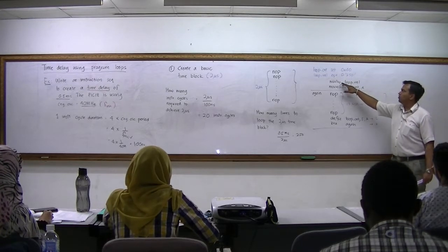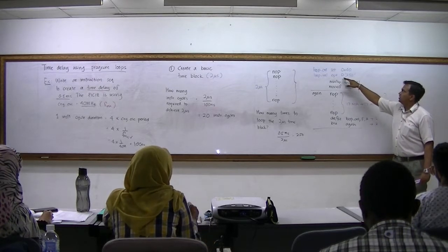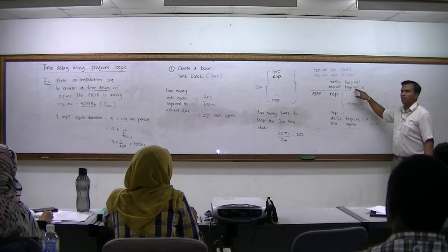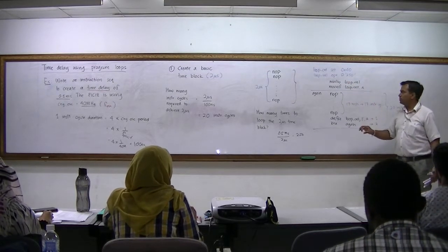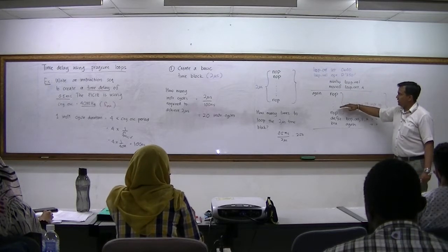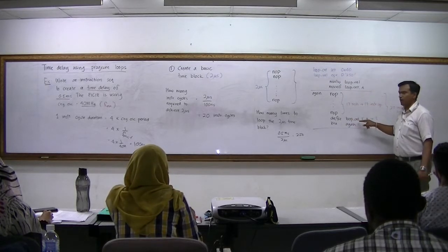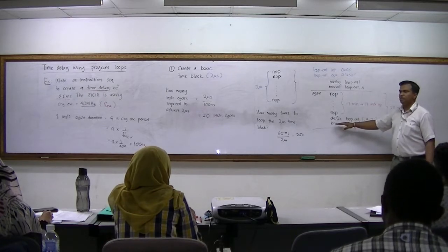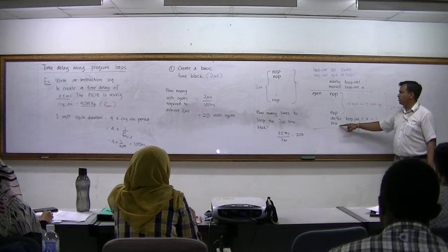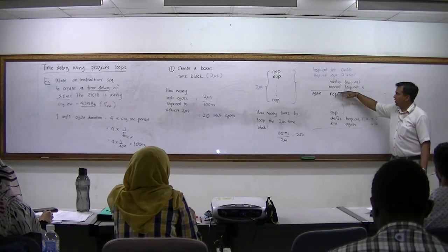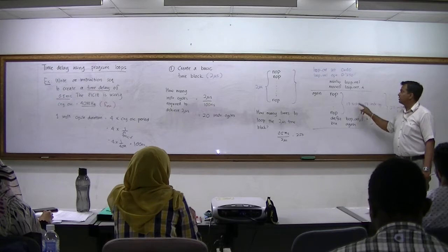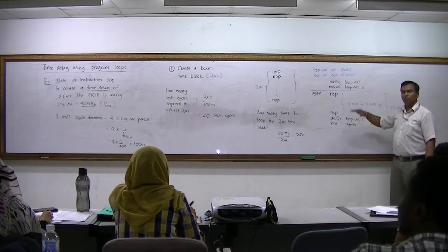So you see, move literal to loop count. The loop value is 250 and you load it inside loop count, which holds the loop value. So you're going to repeat these 17 NOPs and then decrement loop count. This is skip if 0. So if it's 0, it will go out of the loop. If it's not 0, it will branch again. So the content of loop count is initially 250, decimal. So how many times will this whole loop go?